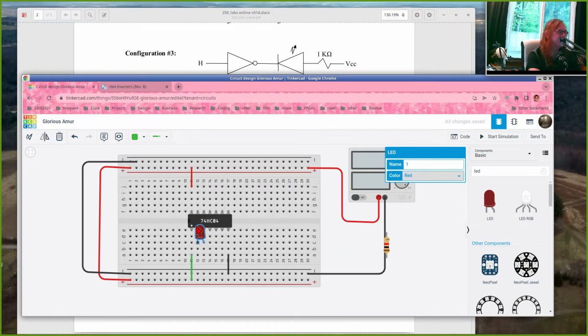And so here's another place that you can have difficulties. If you try to put your LED right here, well, I've got the negative side connected to pin 2, that's great. But look at what's happening to the positive side. It's in the same column as pin 3. Right, so I've connected pin 3 to the anode of my LED. And that's not part of this circuit. I should only have a single inverter, which is input 1, output 1.